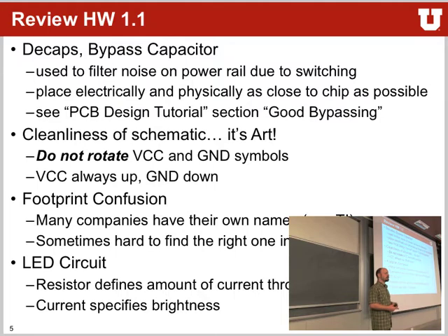One of the things that I see all the time with beginners of schematic design is that they rotate VCC and ground around. Do not do that. It really confuses everybody that reads a schematic. VCCs always go up, grounds always go down, because it's basically like the flow. VCC comes from the top, power goes in and goes out on the ground. So don't try to have a ground symbol upside down.